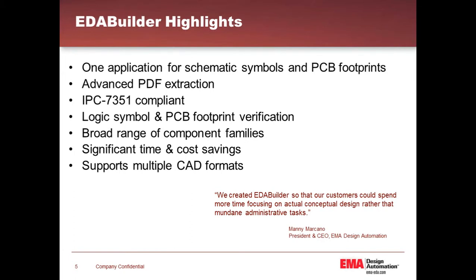And then finally creating the IPC compliant footprints. So all this is done in one tool with other features like linking library, so you have pointers from the logic symbol to the footprint. You can share attributes between the symbol and the footprint, and you can also do cross-probing to highlight elements.